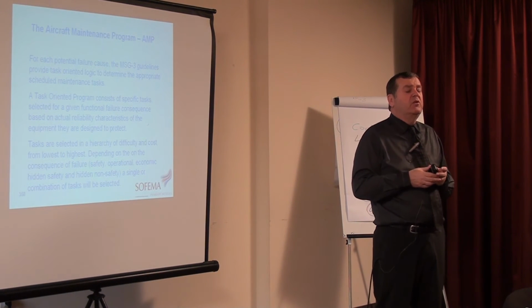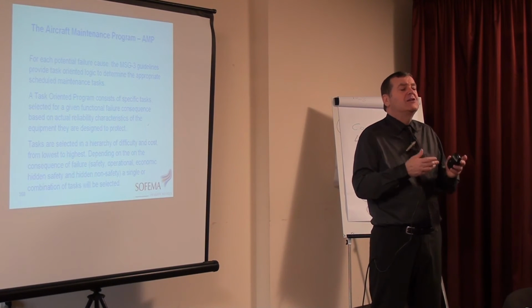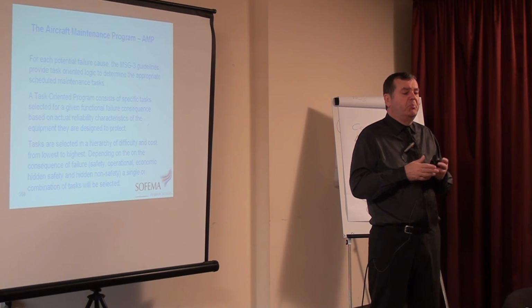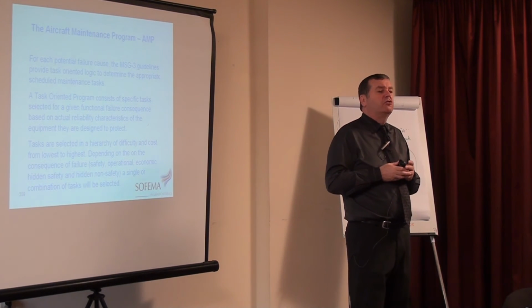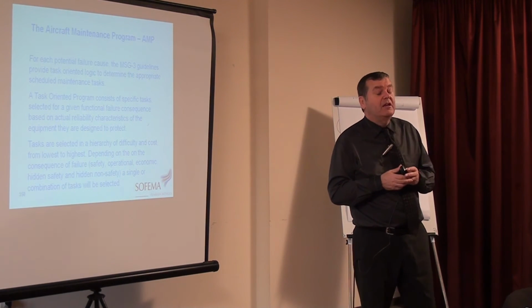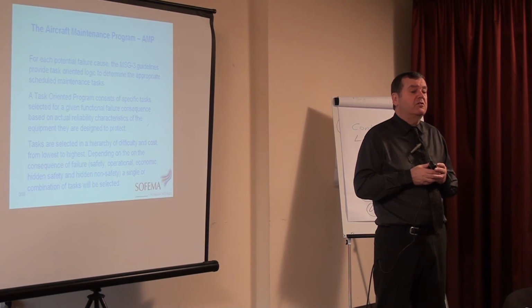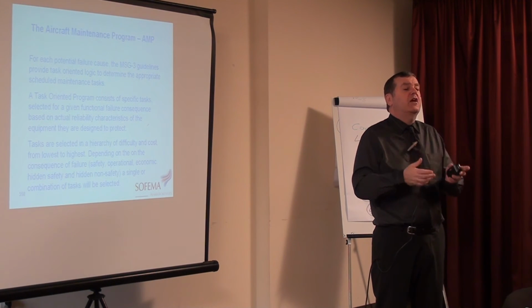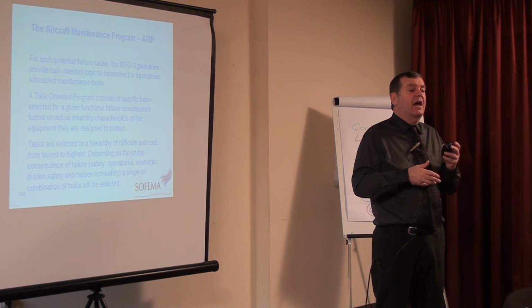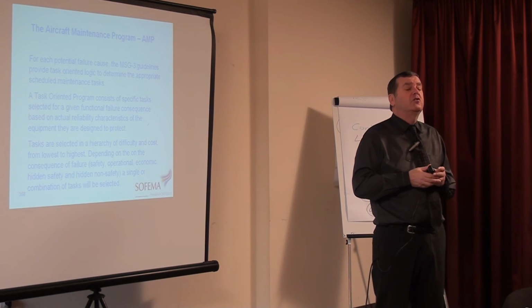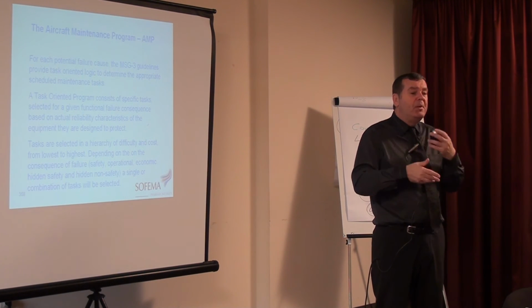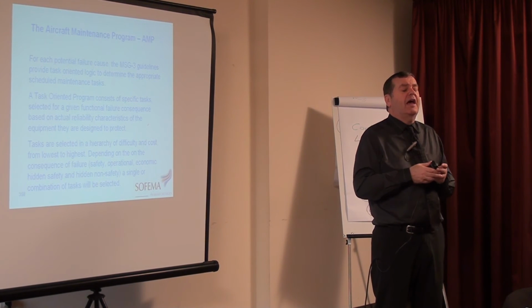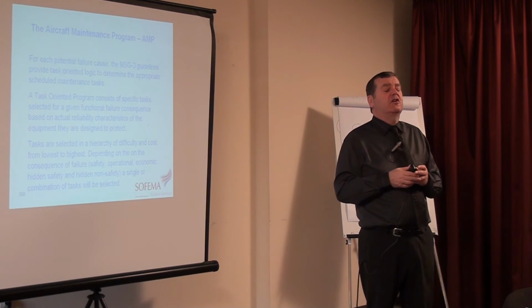If we look closer, we see that, for example, in the hydraulic and flight control systems, both flight controls and hydraulics are essential systems on aircraft. So we will typically see multiple hydraulic systems, and we will see flying controls with dual hydraulic actuation. So, for example, the aileron actuator is operated by two separate hydraulic systems. So we can have a failure of a hydraulic system and we still have full use of the flying control. So this built-in redundancy allows us to have some flexibility in terms of the operation.